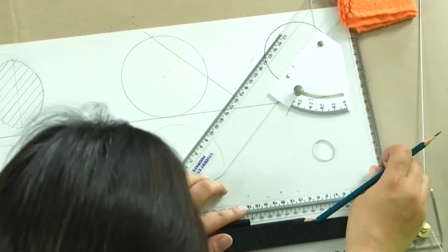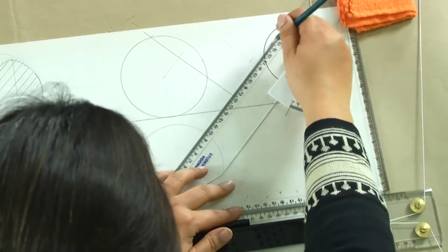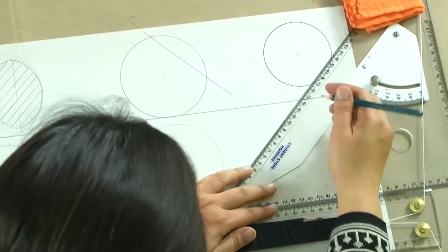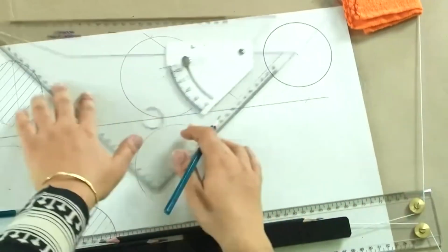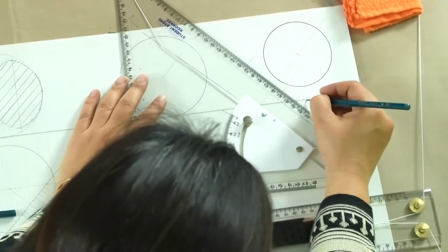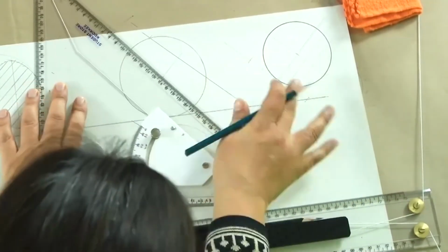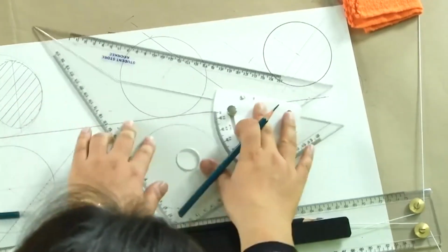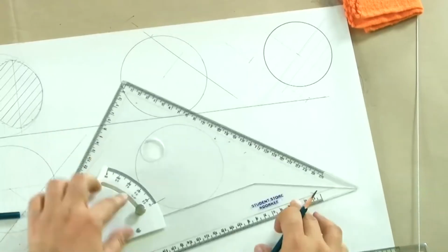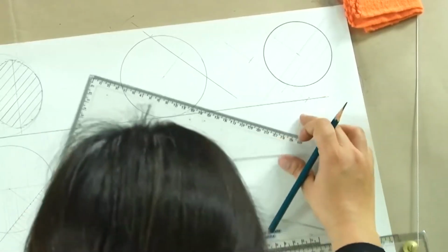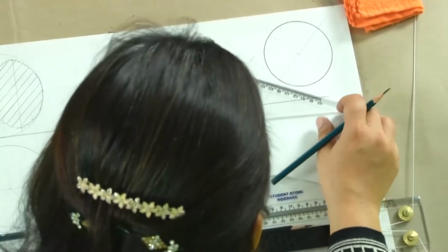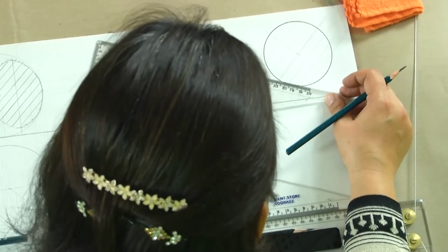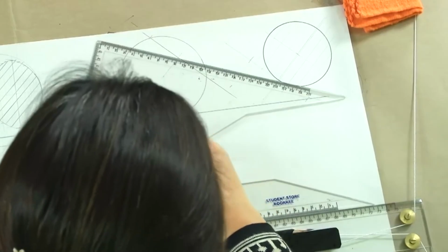So we just have to project these projectors. We just have to take these projectors back onto this line, which was the section plane, the line of the section plane. So we trace exactly the same projectors here. If it was right here, you could have just projected them here, but right now, what we can do in this case is we can always have a line which is inclined such that we connect. So it's not the best way, but you can always do that.